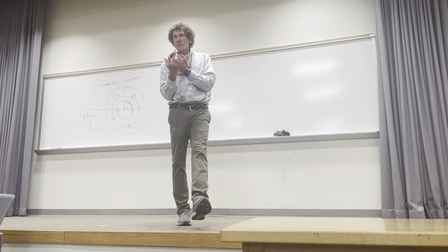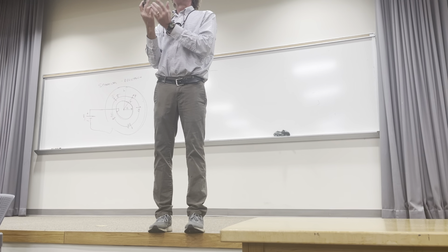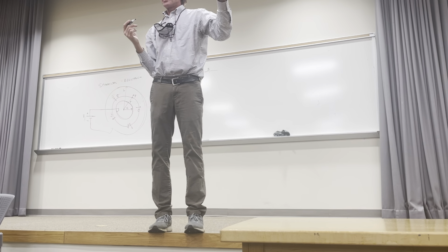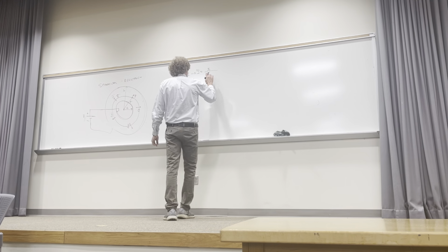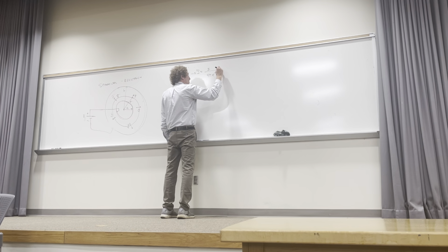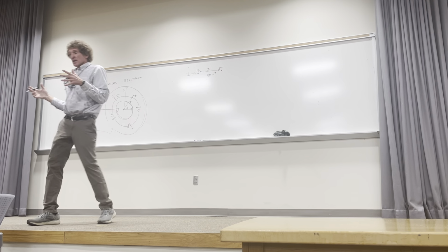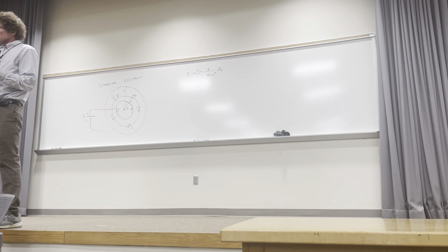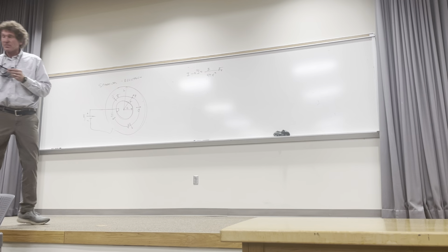Remember, I'm at a distance R. What's the surface area of a sphere, everyone? 4 pi R squared. You need to know that, right? Surface area, not volume. So it's 4 pi R squared in the a_R direction, meaning the radial direction. That should make sense. The current I is flowing, it's the same current through every spherical shell. Imagine this, as you change R, the same amount of I has to flow through it.